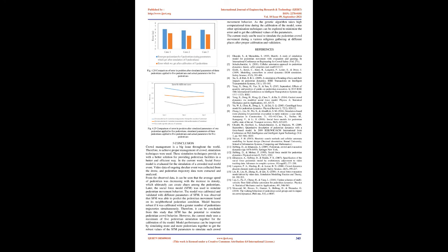In the above figure 4.18, 5 pedestrians were simulated with the help of the social force model. Black and blue circles represent the simulated positions of pedestrians, respectively. The yellow line shows the desired direction towards the destination. In this figure, pedestrians are moving approximately to their actual position, which is obtained from video analysis. Therefore, this calibration can be extended to other pedestrians to check whether it is working for a large number of pedestrians or not.